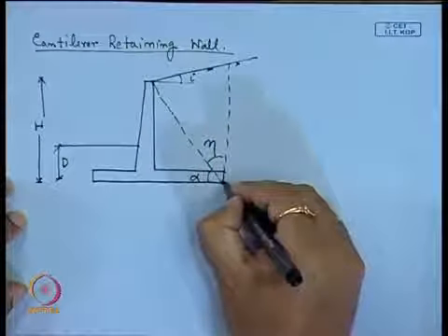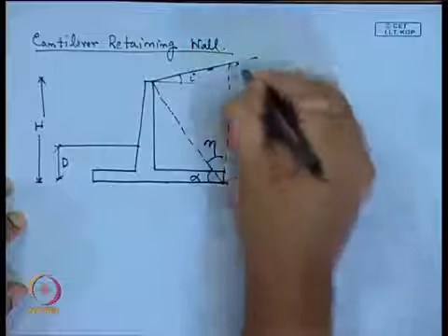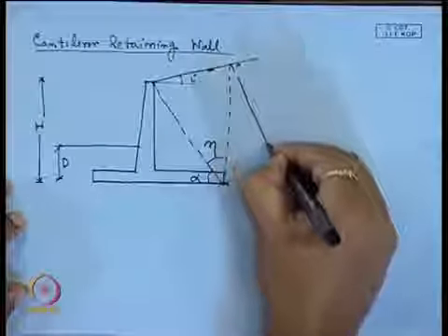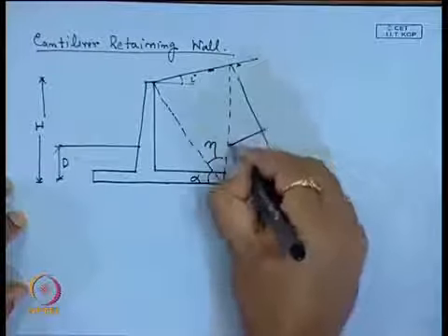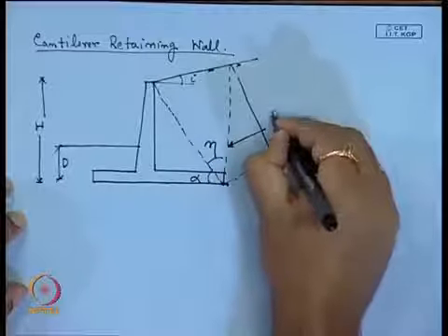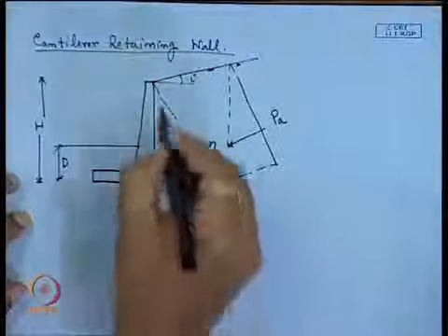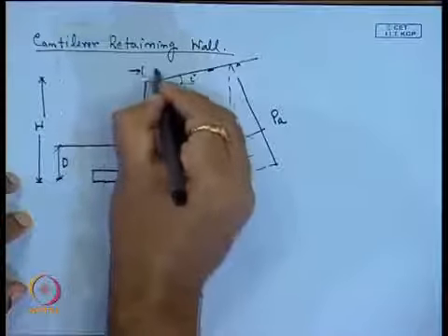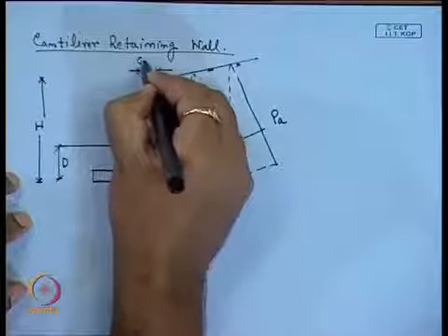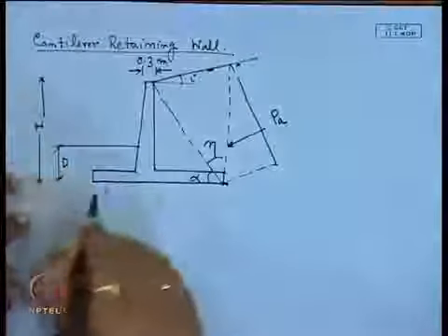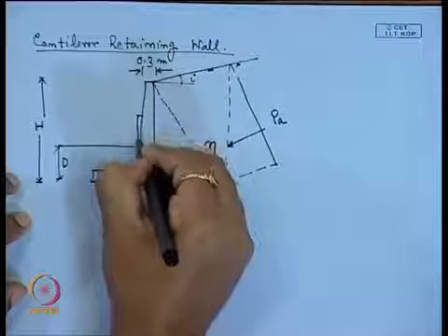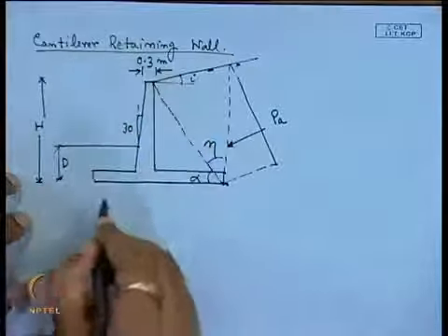now this is the earth pressure distribution. So, this P A will act parallel to the ground line, and now the recommendation is that this top portion is 0.3 meter. Now, this angle is again 1 by 30.